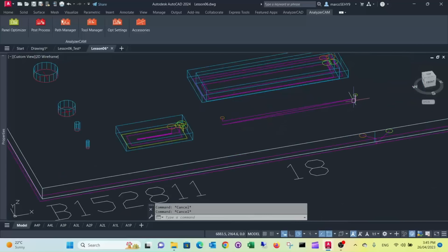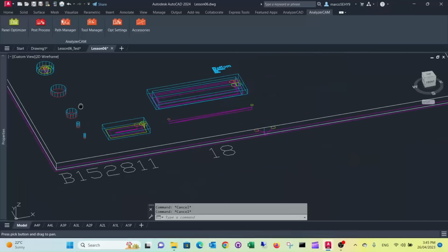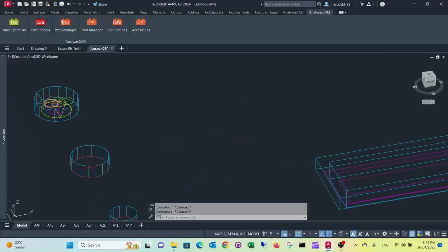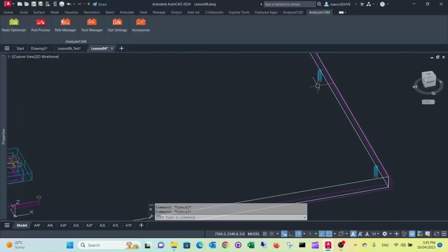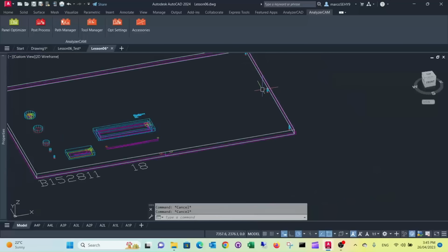This is our groove. Our groove has a tool that does it in two runs. As you can see, there's 2 tool paths for it, and this is our pocket, 12mm deep, and they are our drills. And the 40mm one is a rounded C pocket, a circular pocket. These ones are the drills from our touch type end panel. They've been done automatically, we don't need machine blocks for that.